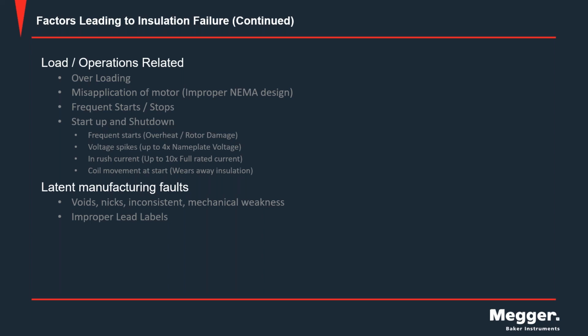So a motor is going to keep on trying to do it. So we put protection systems around it during startups, during normal operation. We should also put protection systems around to lock out operators if they've been started too many times within an hour. It's causing higher heat and can cause rotor damage and insulation damage.